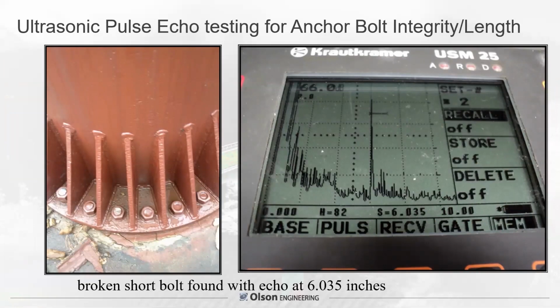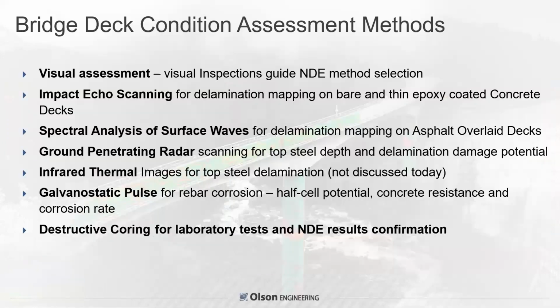So this example is taking advantage of the flaw detection. You can't really do this well with a thickness gauge. You get a result, but you want to see the data when you're looking for flaws. So, comparatively testing and knowing the anchor bolt lengths that were supposed to be there, this is a broken anchor bolt. It's showing on the screen of the unit a 6.035 inch echo that is a short bolt. It should have been a 2-foot bolt in this case. So this is a good thing to check on anything where you might have broken anchor bolts. The unit we use can go out to 32 feet for some very long embedded bolts. Most units won't go quite that far.